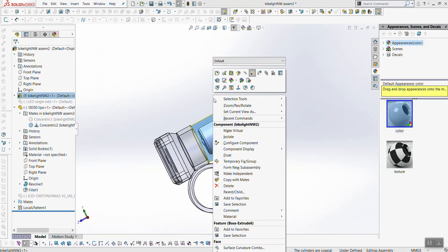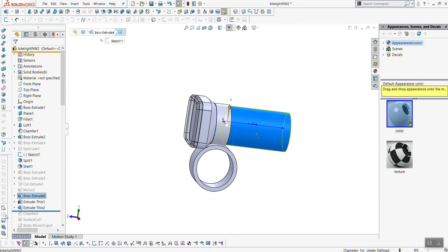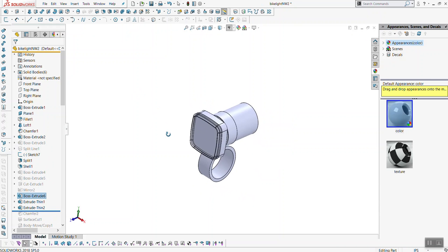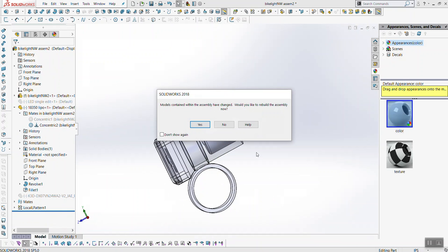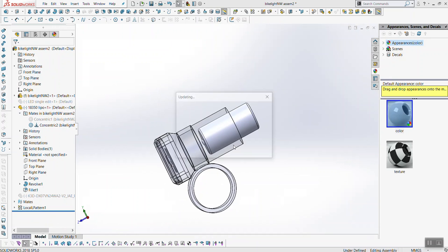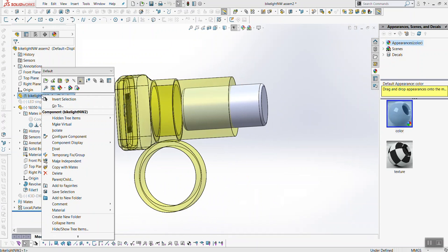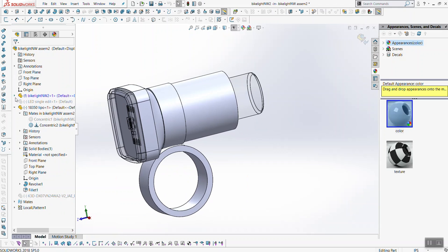Now, hypothetically, I've already adjusted this file so it matches. But let's say I was following my sketch, and maybe my sketch was a little bit optimistic. I wanted my light to look a little bit slimmer aesthetically. Well, now when I'm in my assembly, I realize by getting those guts in there that it needs to be longer. And again, just like we talked about in the past, you can always right-click on your part file, go to Edit Part, and now you're working on your part within the assembly.